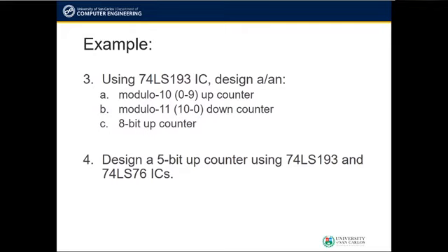For the next example, let's try to design a modulo 11 down counter that counts from 10 to 0 and then repeats. The circuit in Proteus will look like this.